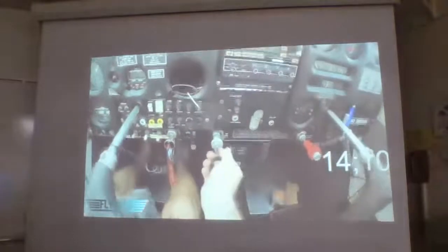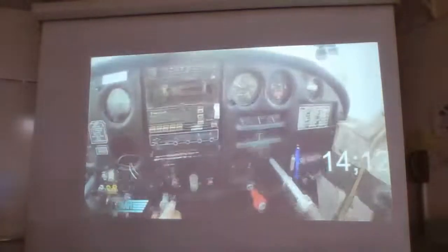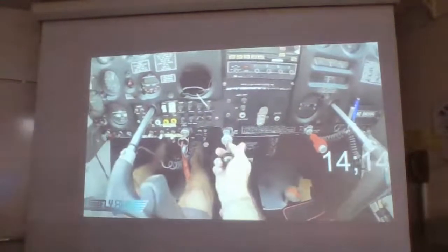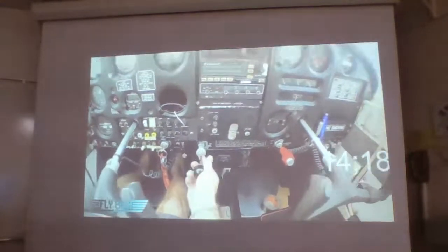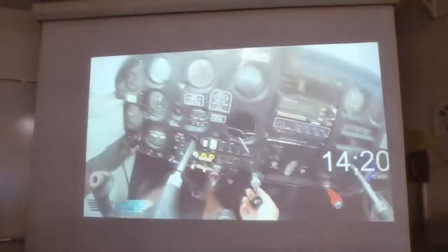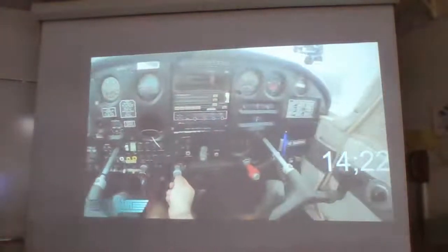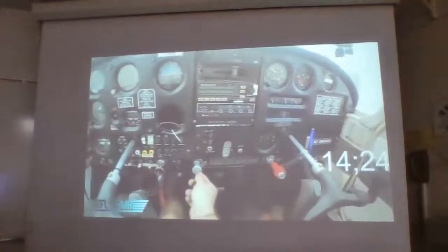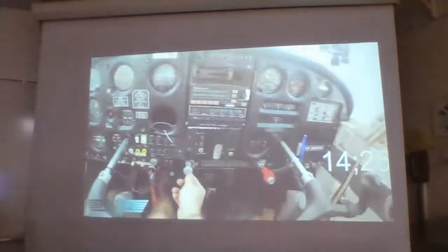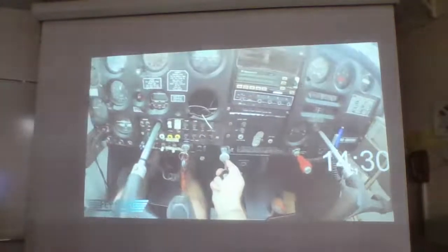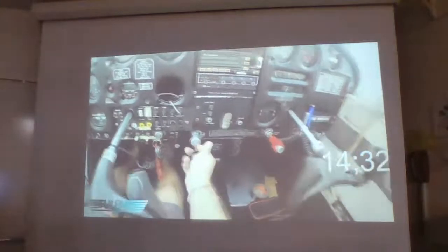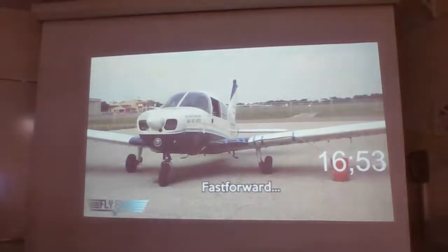It's still running. It doesn't like to run full throttle. That really makes it want to shut off. Oh, come on, catch. It likes a little bit less, maybe half throttle. It's giving me about 1,200 RPM, but shaking like crazy. Obviously, in flight, I think I probably would have voluntarily shut it down by now because I'd be afraid of something really going wrong. Wow, it's shaking. Come on. Oh, it feels like one cylinder is running.